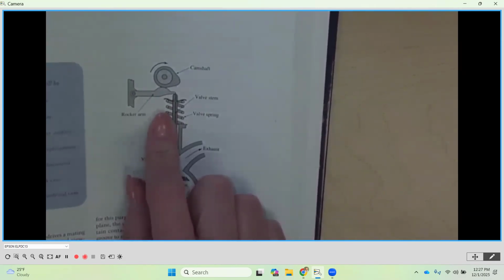however long I'm saying, if this needs to go down, let's say I'm going to take 1 second to go down 1 inch. And then I'm going to dwell, or wait just another second. And then I'm going to go back up in one more second. That would mean that my motion is T1, dwell for T2, and then T3 would be coming back up. Now, all of those 3 sequences are going to happen in one revolution of our cam.